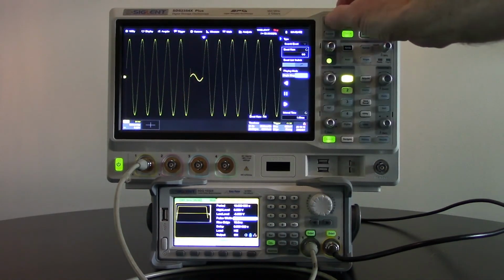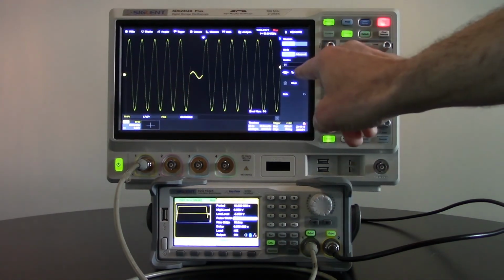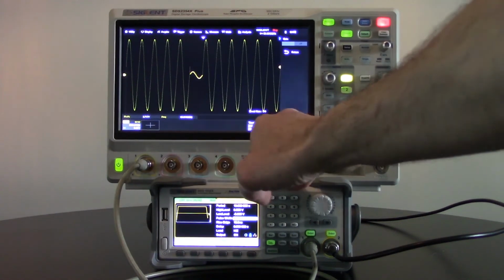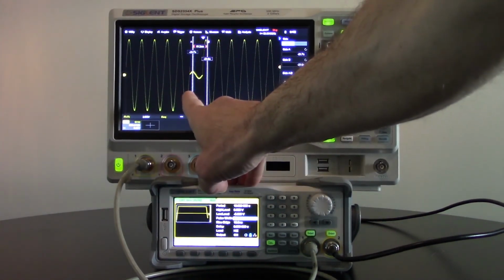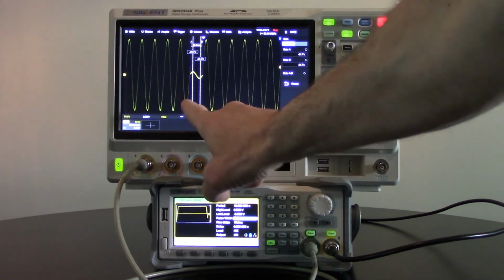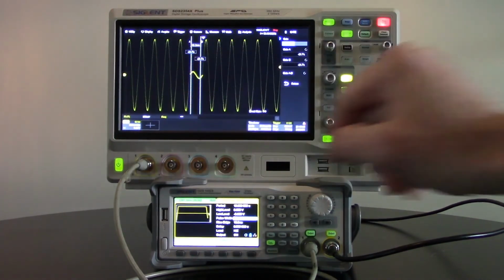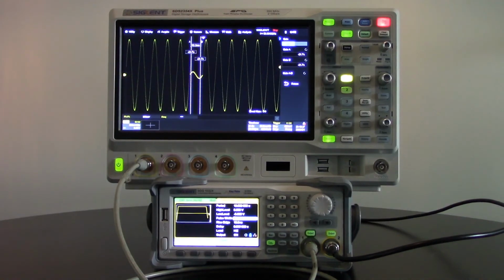I can also turn on measurements, and with measurements we have the ability to turn on a gate. Now I can turn on a particular gated measurement, and I can move that gated measurement and just look at the voltage values in that particular area. So you can see 360 millivolts. So I have a fairly significant drop in that particular measurement or that particular amplitude for a really short period of time. So search and navigate can be extremely helpful when you're looking for that needle in the haystack.